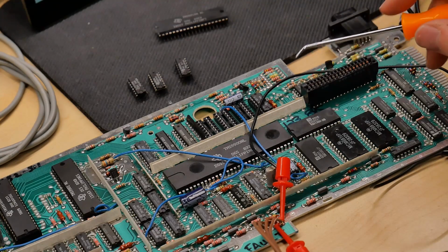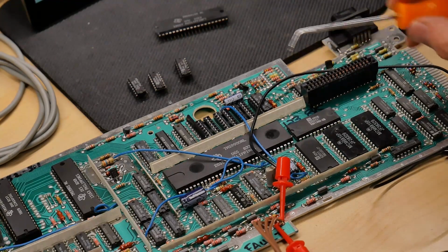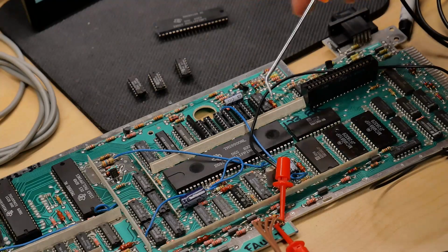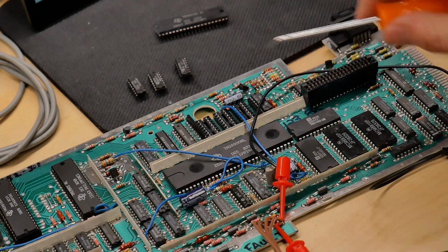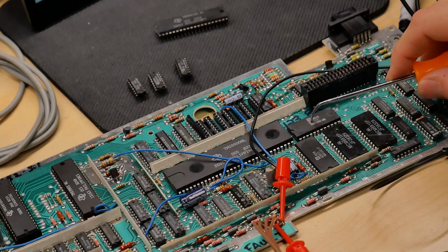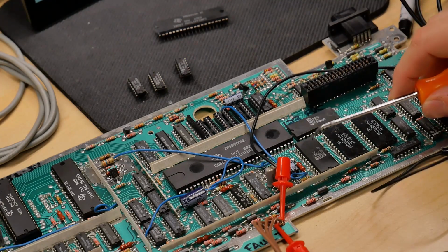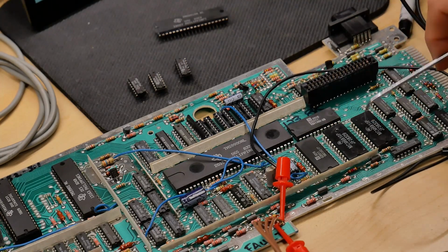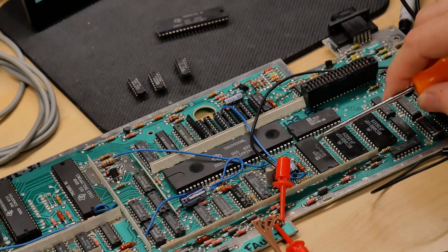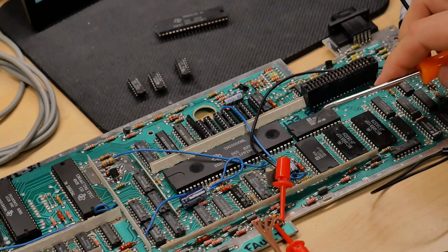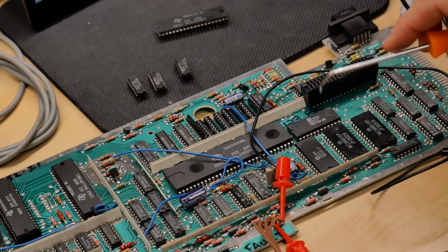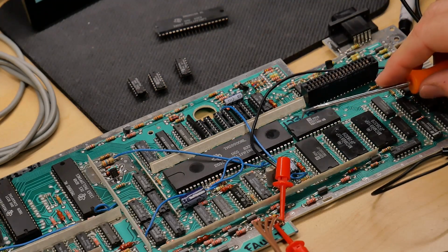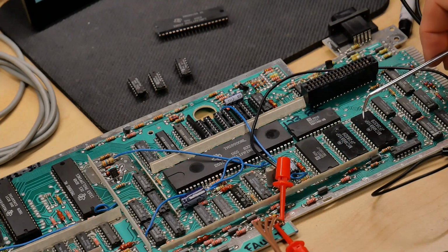Okay, those of you who troubleshoot the TI were probably screaming at your screen. So these 3 chips are the GROM chips, but I was kind of dumb in interpreting the instructions because these 2 ICs here are ROM chips, and these are on the 16-bit bus with the RAM chip. So these 4 ICs are all hooked up directly. So the ROM is split into 2. I think they're 4K each, and there's 2 of them. So absolutely, positively, the ROMs could be the problem as well, and the RAMs.